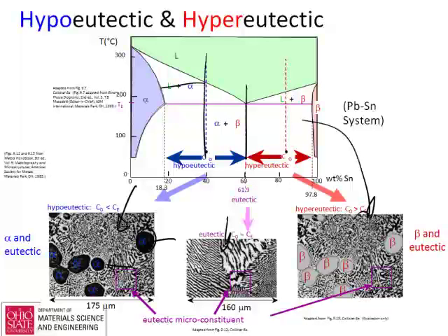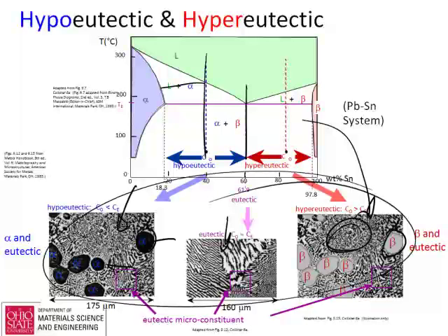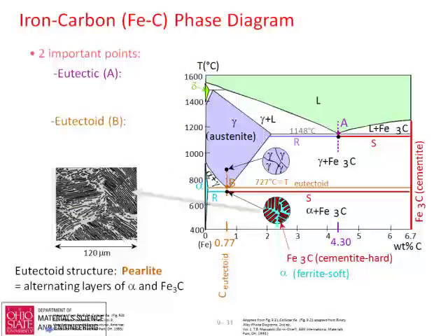And then if you're here, hypereutectic, this is the lead, the tin, that solidifies first. And again, you get this eutectic structure in between, which is this very fine mixture of two solid solutions. So again, hopefully these micrographs can give some meaning to your students between mixtures, solutions, and so forth.